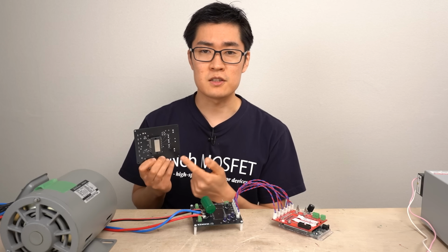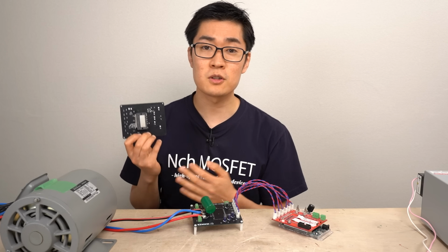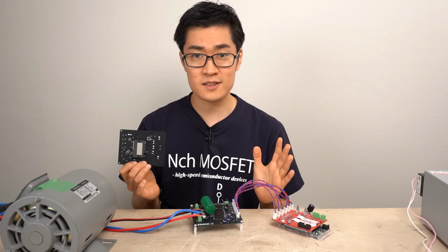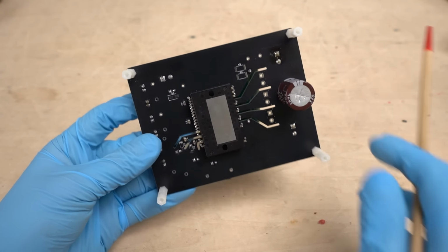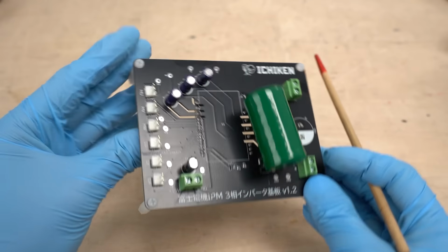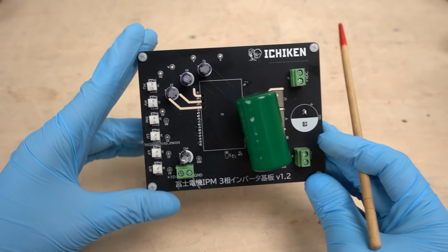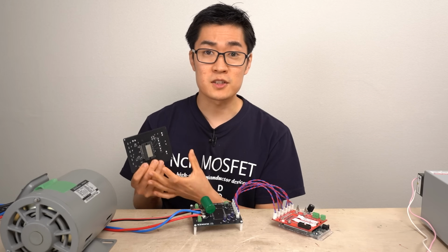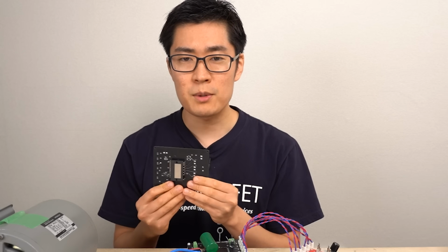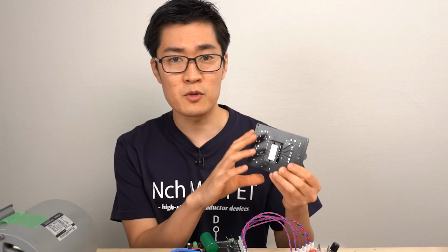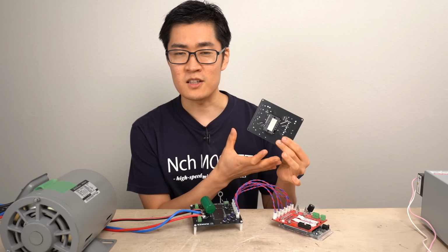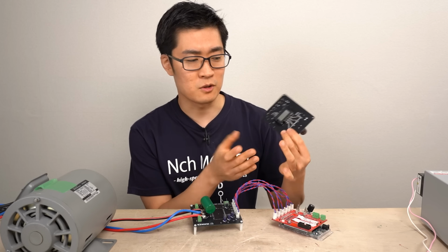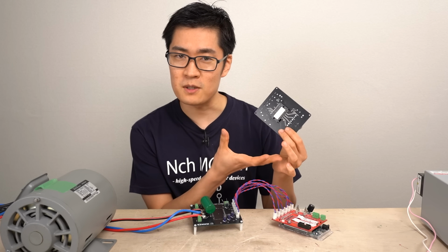While IPMs may not offer quite as much flexibility as discrete power semiconductors or conventional power modules, their simplicity and convenience more than compensate for this limitation, which is why they're such a popular choice for a wide range of household and industrial applications. I built a three-phase inverter with an IPM myself, and by doing so, I was able to greatly reduce the number of components and make the entire circuit much smaller and more compact. IPMs are really convenient modules, so I definitely recommend thinking about using one if you're planning to build an inverter.